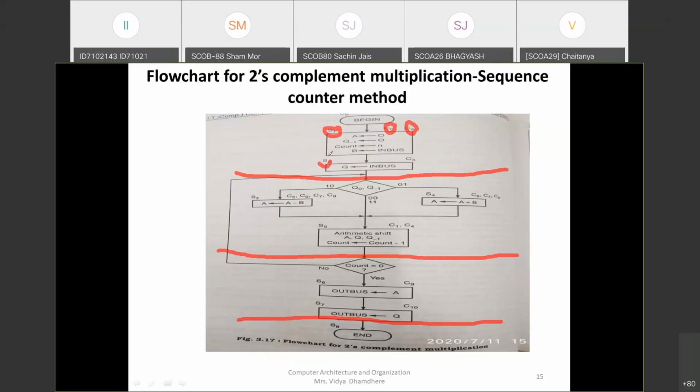Now for that sequence, the next sequence number is given. That we have done in one phase. If you observe, the first phase is phase 1. So what control signals are generated for this particular sequence? You can say that C0, C2 and C3 are the control lines generated or activated in phase 1 whenever we are initializing the parameters of Booth's multiplication algorithm.